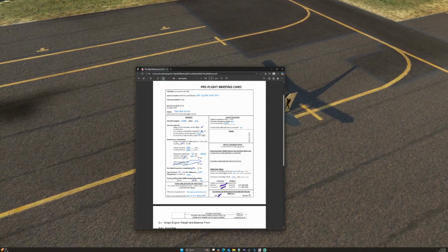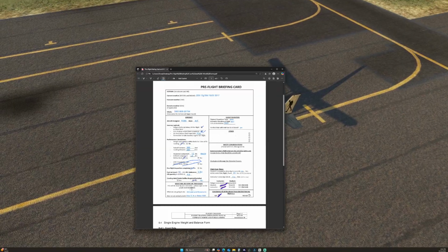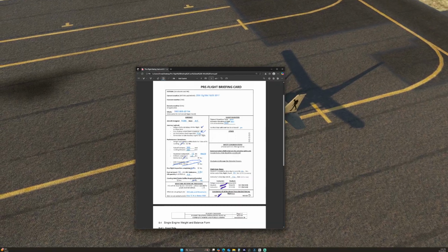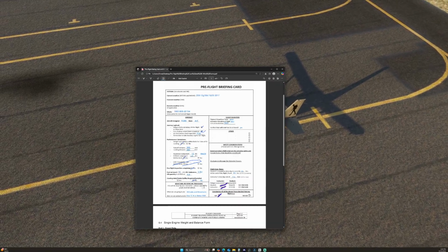So the cowling inlet and outlet baffles are not actually required until the temperature gets to around a pretty steady -6 degrees, so it's not really cold enough for the baffles.